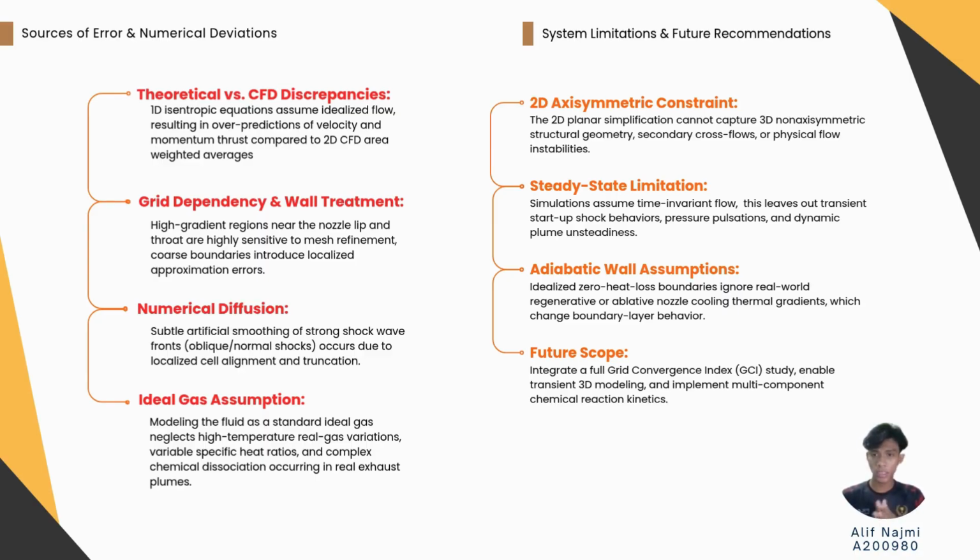In terms of limitations, treating the exhaust gas as an ideal gas ignores the high-temperature variations and chemical dissociation. Furthermore, our 2D axisymmetric approach cannot capture asymmetric 3D flow separations. Lastly, our steady-state adiabatic wall assumptions omitted the transient startup shock wave.